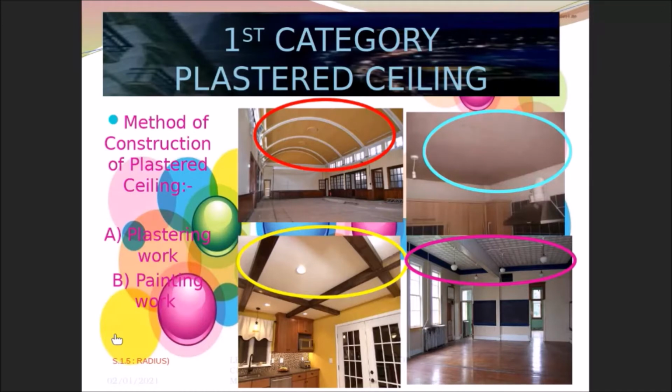I remember last semester we had one question in the final exam: take off the quantity for all items in the building finishes under S.1.5. So students have to check the layout plan and only need to measure any component of the building finishes at the curve. Whatever item is not curvature, you don't have to measure. That is the key point.